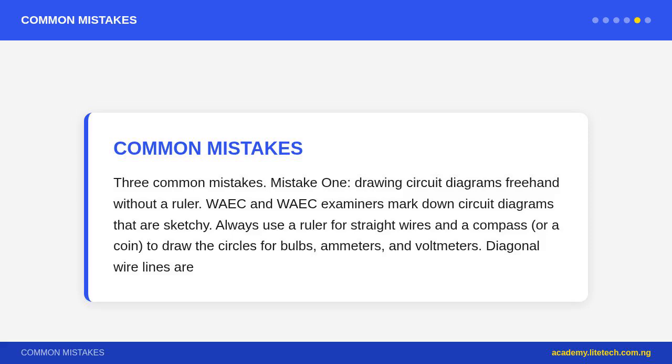Mistake 2. Placing the ammeter in parallel instead of series. An ammeter must be connected in series, in line with the component, to measure current flow through it. If placed in parallel, it creates a near short circuit. Ammeters have very low resistance, potentially damaging the meter and the circuit. Remember, ammeter equals series, voltmeter equals parallel.